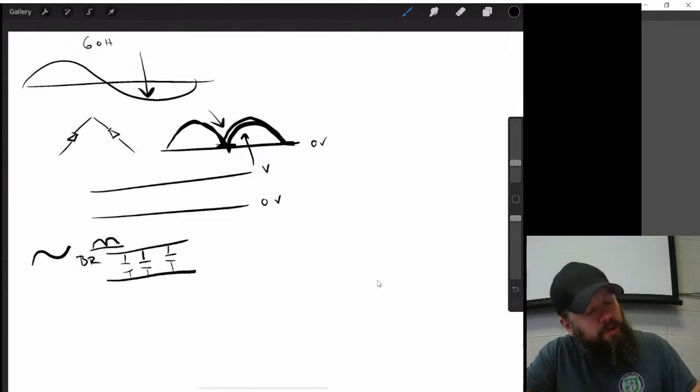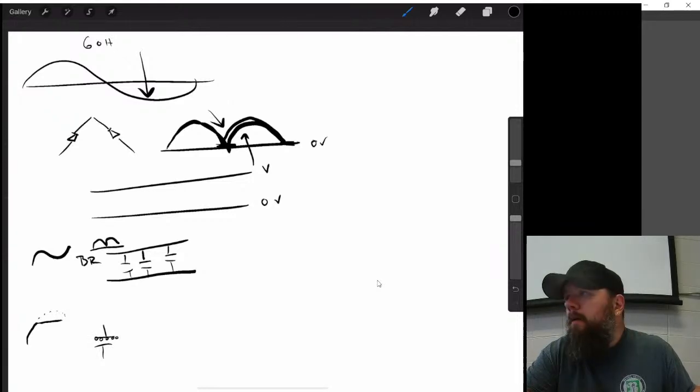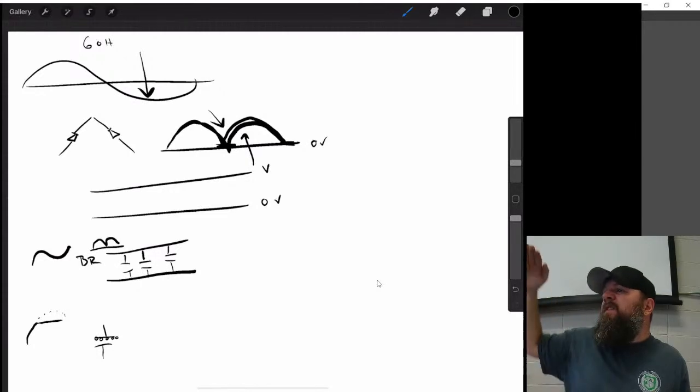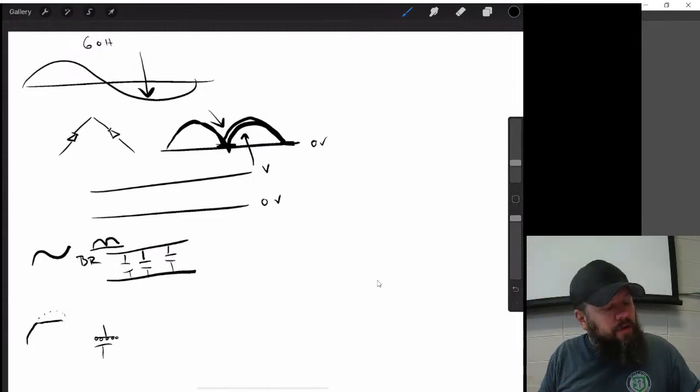When we get to a certain point, it takes all that extra, so it would have kept going up, right? And it starts charging up and starts putting electrons on a plate of the capacitor. Okay? So it starts smoothing off the top of it, right? Or cutting off the top of it. And then whenever it starts trying to dip down, right? Those electrons go out to supply a little bit extra power, so it doesn't really dip down anymore.